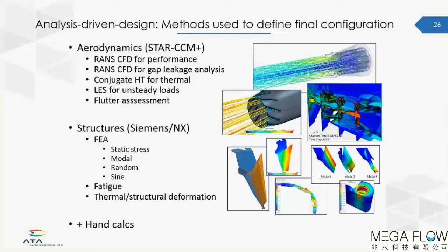On the structural side, using NX, we also did FEA in terms of static stress, modal analysis, random and sine analysis. We did fatigue analysis, and we also did analysis for thermal and structural deformations. And of course, there were many hand calculations that the designers had to do. So this was really an analysis-driven design.